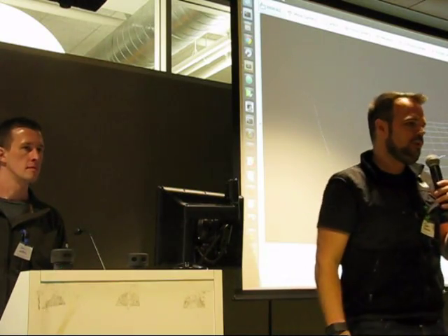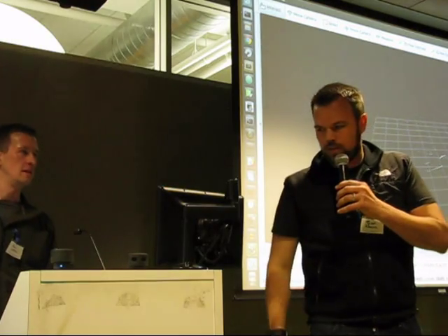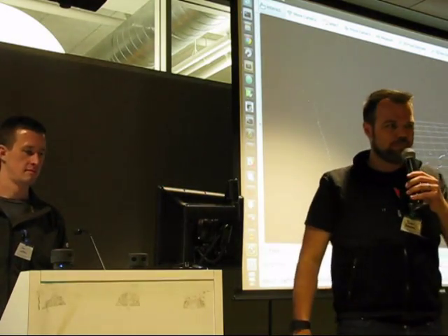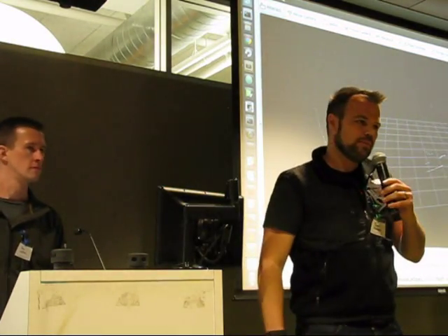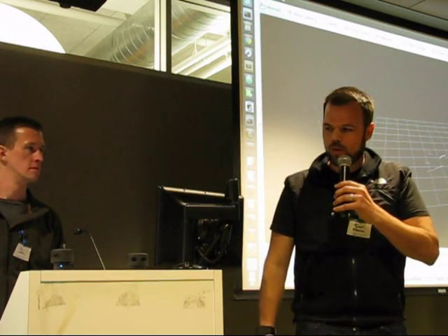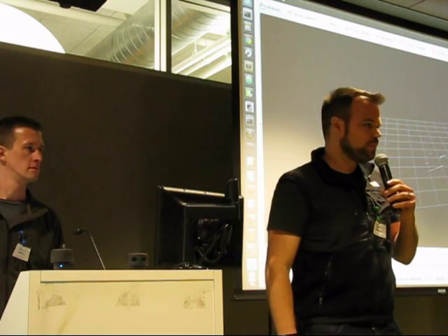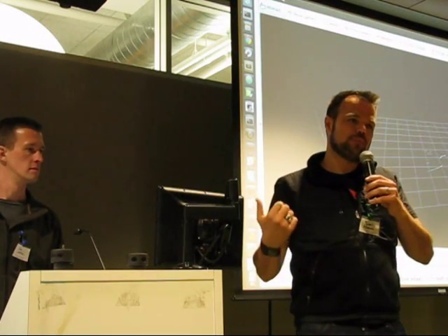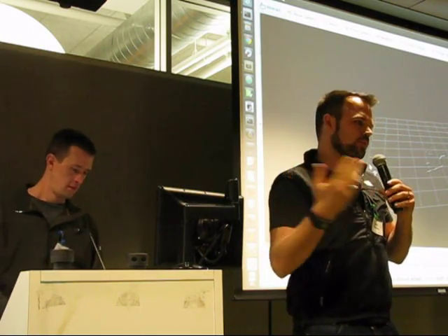So what's the interface to it? What does it give you back? So the basics are UART. Then we're also providing a UART to USB adapter. So just high-speed serial. Yeah. And we're going to be providing SDKs for all the major languages.